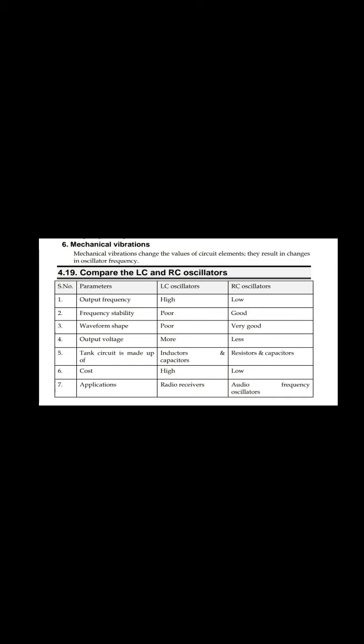Use a negative temperature coefficient capacitor to prevent the warming effect. Stability can be improved by using a temperature compensation technique. We can also use a temperature controlled chamber to minimize temperature effects, that is, we maintain AC in the room. Supply voltage variation can be handled by using RPS. So these are the remedies for instability in an oscillator.